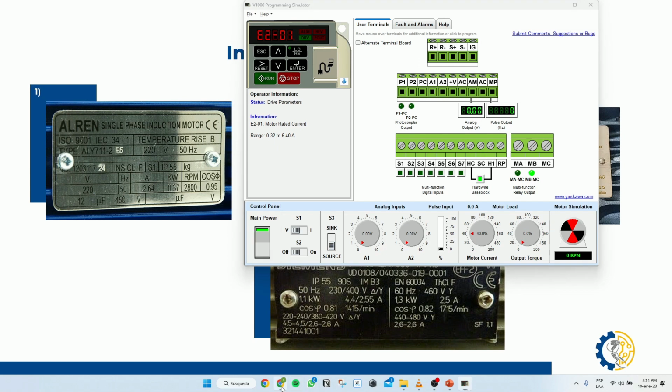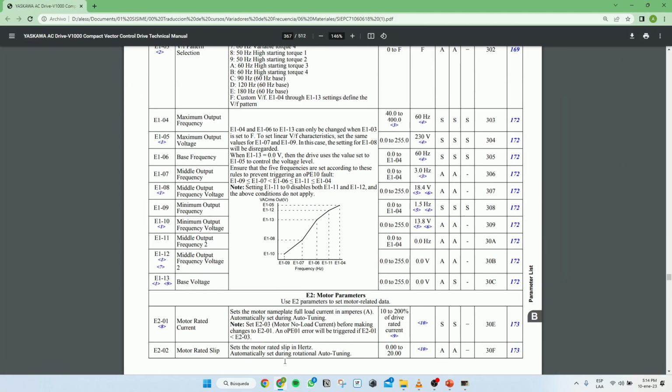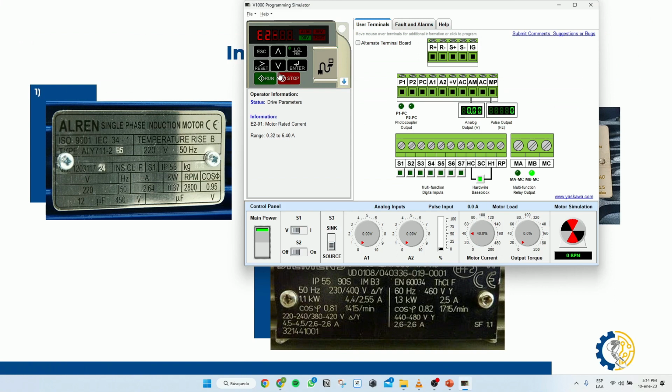And then what is our manual telling us to do? So this is the drive average. We don't have this data. So this is the data current, which we don't have. So these are parameters. And as you can see, these are additional parameters, which the more we fill, the more optimal the motor is going to be. So we generally don't have this data. Okay, so pole numbers, that should be 4.